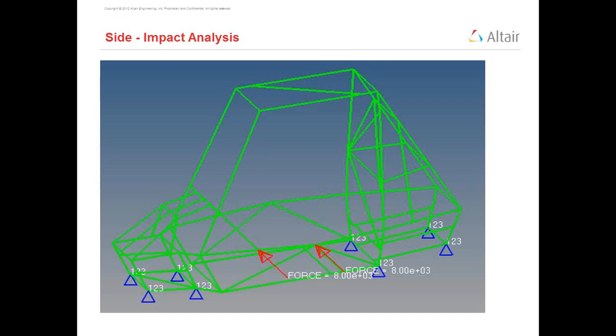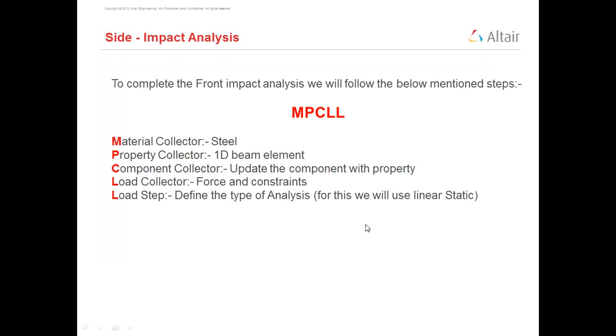So if you can see here, these are the forces I have applied. So I will create one collector for forces and a different collector for constraint. So we will create two collectors for forces and constraint. Then I will define the load step. In load step I define the type of analysis I am going to perform. So this is the process I am going to follow.